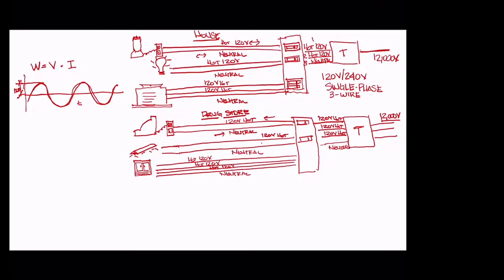And this freezer is not going to be like this air conditioner here in the house, well, that one was 2 120s in phase. So it's going to give us 240 volts. This one is going to be 208 volts. More on that in a second. Actually, let's talk about that now. Why on earth, if we added 3 120s, would we get 208 volts?